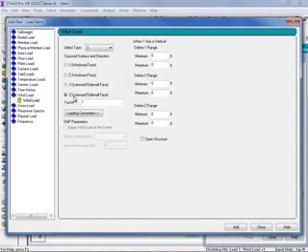We will select our -Z leeward or sidewall face. And for the first sidewall, we will enter a factor of 1.0. Click Add. And then we will also add an additional one with a factor of -1.0. And then we'll click Add. This concludes our load items within our wind load for our positive X global axis direction, so we will click Close at this time.